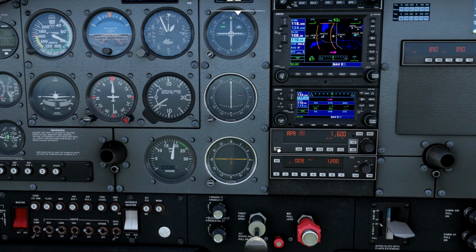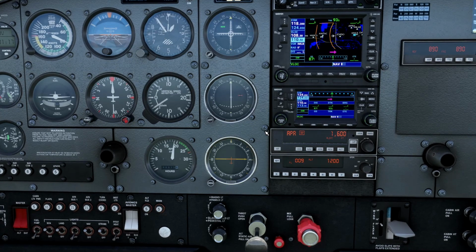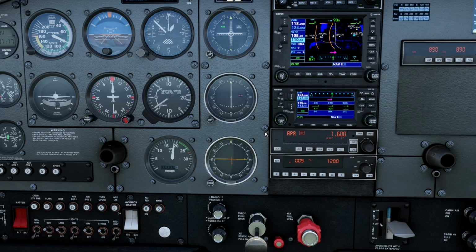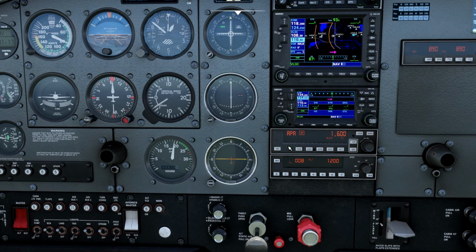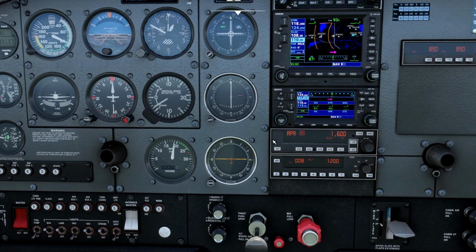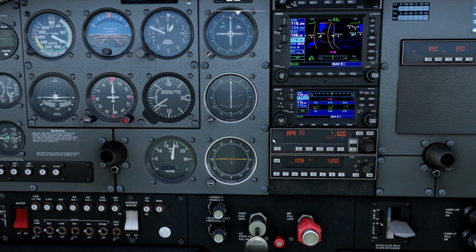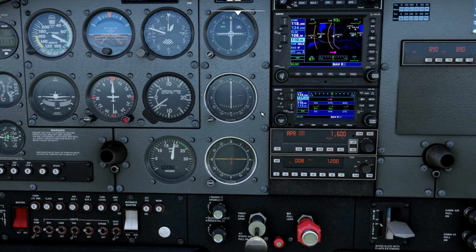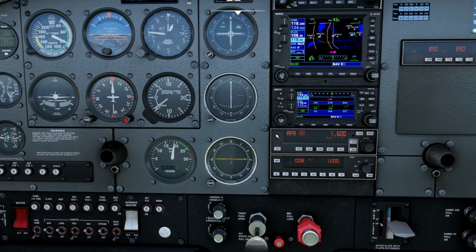And again, you can disengage it. I like to use the autopilot toggle master control assigned to a key on the joystick so it's easy to turn off, but you can also do it with the autopilot disengage button. I would not try to override the servos at a low altitude. You don't want to get yourself into an unusual attitude at 200 feet off the ground in a low visibility condition. That is not a recipe for success.